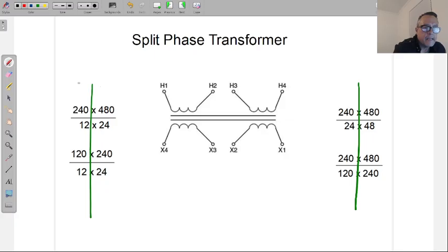And if we are, for example, connecting the primary side to 240 volts, because that's the voltage that's available nearby, we got 240. And yeah, exactly, on the secondary, I know in person you guys have gotten this, but online is not, so let me just run it through that. Very good. We are on parallel sides. If I want to get the secondary 12, then we're going to hook up our transformer in parallel.